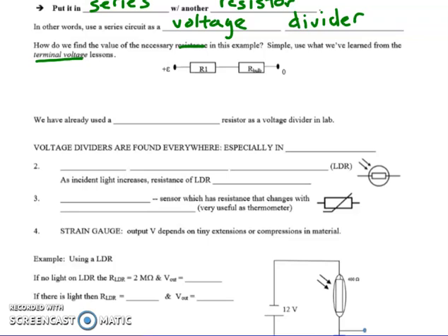This is not the only approach. If I know the power that the bulb is supposed to get for the voltage, then I can figure out how much current it should draw when it's working correctly. So I can use the relationship P equals IV, where I know I'm going to get 3 watts of power when I connect it to a 6-volt source. That's how it works ideally. So the current in there has to be a 1/2 an amp.